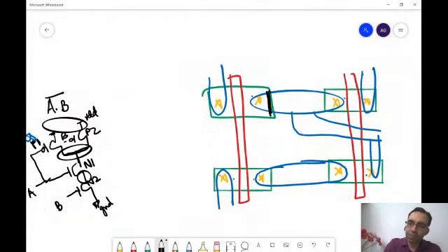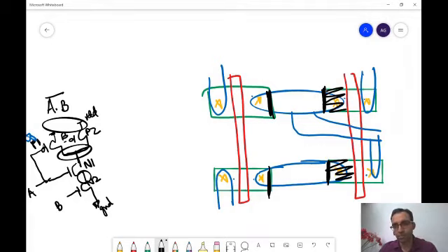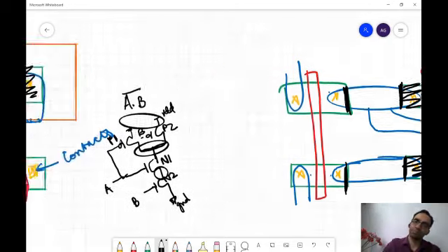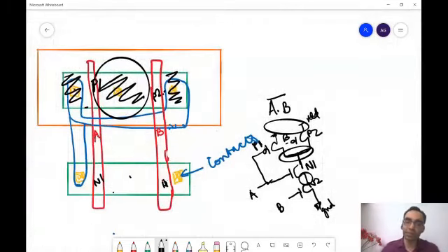I have this sidewall capacitance coming in extra, plus at least one of these drain capacitances is extra. But when I'm extending the shared region, I don't think that will become an extra thing, because the same area would come under the shared region also, right? Be careful about what I said, I said if we go with the assumption.